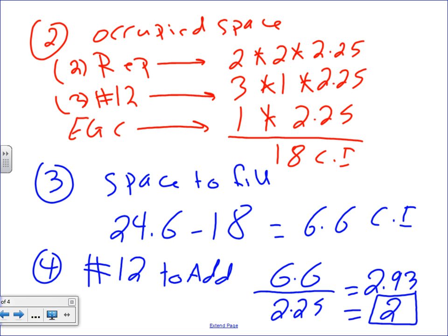Actually, a difference: if it comes through and the loop is less than 6 inches long, it's a one volume allowance. Yeah, then one conductor passing through counts as 1, if you don't make it a loop. So these 2 conductors could be 2 conductors just coming and sitting in the box, or 2 conductors passing through the box. But I'm asking about bringing them to the box. So these literally will be 2 conductors coming from anywhere else and just sitting right there in the box.